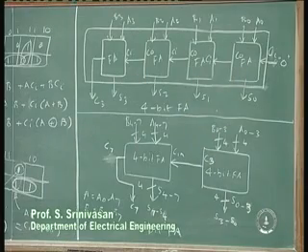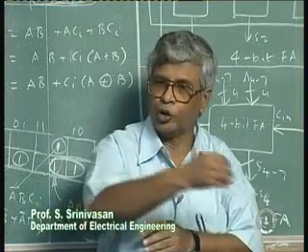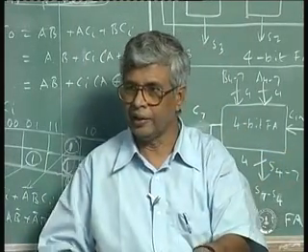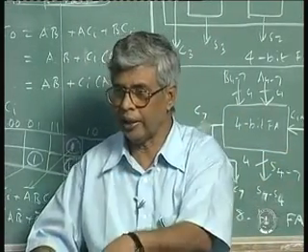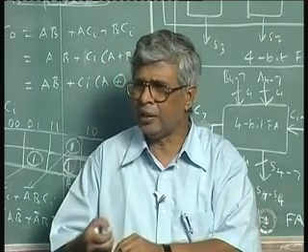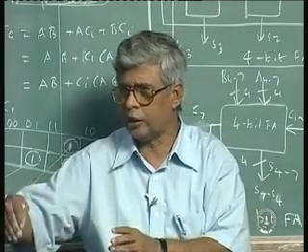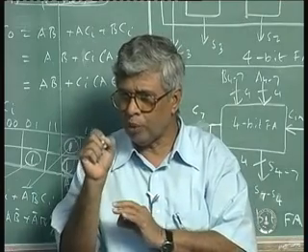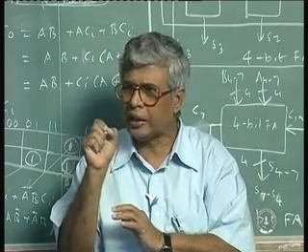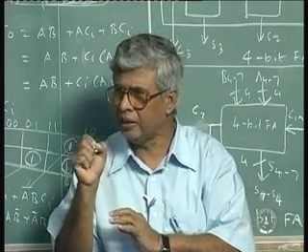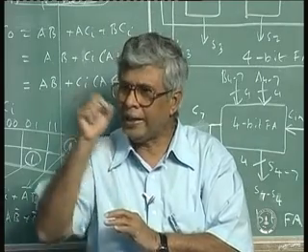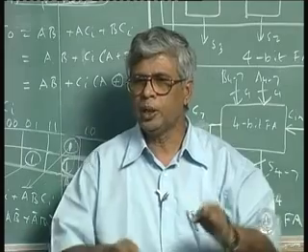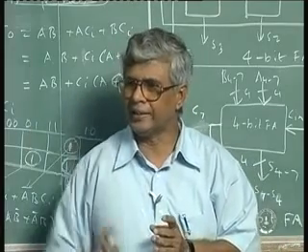As soon as the carry comes, the sum comes, but then the carry goes on. Carry goes from here to here, leaving sum behind. Goes from here to here, leaving sum behind. Sum may be a slightly delayed carry, but before the carry goes to the next stage, the sum would have settled. So if you don't worry about the minor difference between the sum delay and the carry delay, let us only worry about carry delay, because it is the more significant of the two, because it has to travel a long distance.